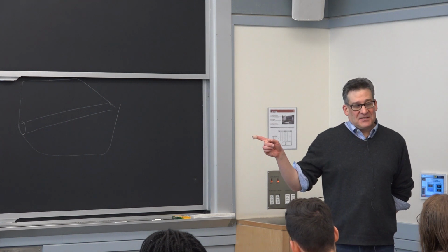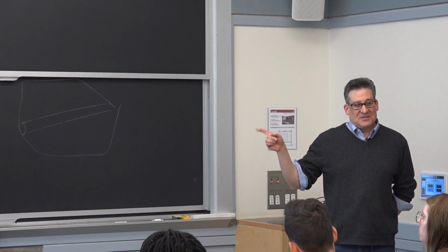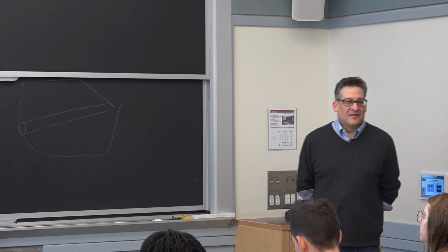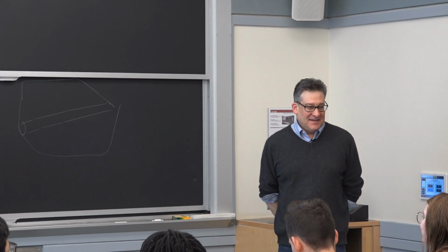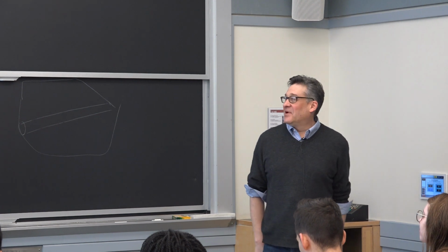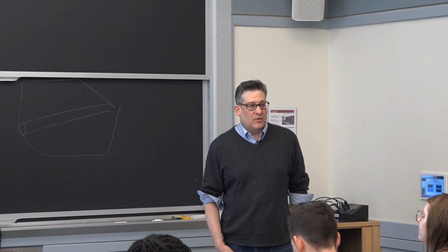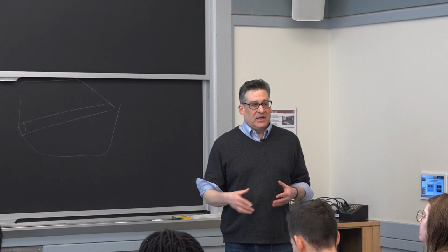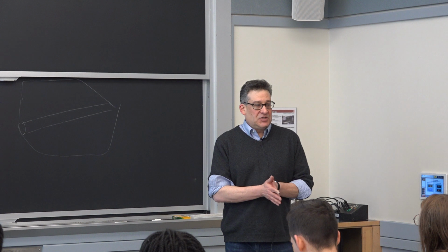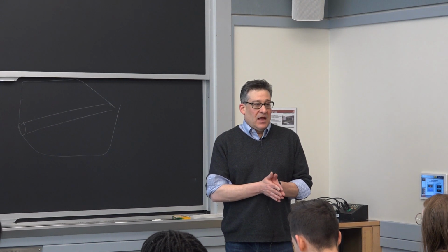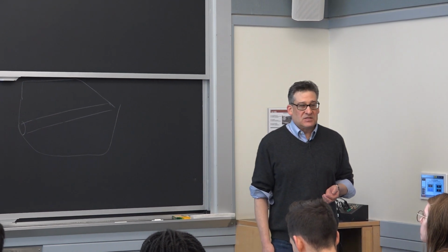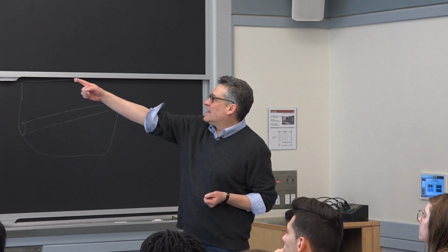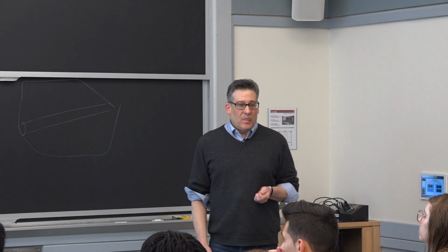Now that you have these equations, if you're really interested, you can go off and try this yourself, because it's a fun game. I've played this a lot. I have a spreadsheet. I'll give it to you if you want it. Kind of nerdy. I'd love to have a spreadsheet. I'll give you my spreadsheet. I've played with this a lot: how strong do you really need to get, how stiff do you really need to get, in order for carbon fiber not to win? There does get to be a point where you can actually do better with steel than you can with carbon fiber. And fiberglass is another example. Fiberglass is horrible in stiffness, and that's why it's the last one, number 6 here. Designed for strength.